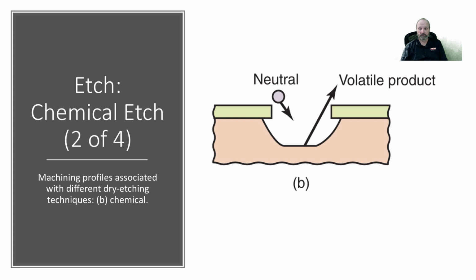Okay, you can also do a chemical etch where you put the wafer in a bath, and the chemicals themselves will react with the material that's available to it. It will create a new molecule, right? It'll react and combine, and then that comes off of the surface. And those tend to be isotropic etching, which means the same etch in all directions. So you get this hemispherical or dish-like etching there. You can have wet etching, chemical etching, that is anisotropic, that has definite directionality.